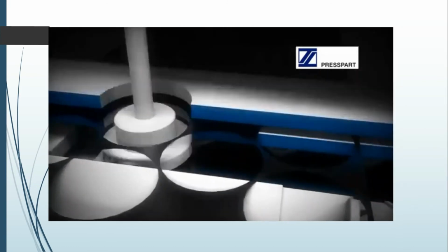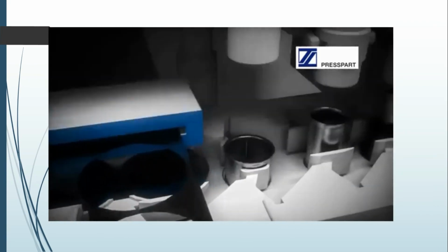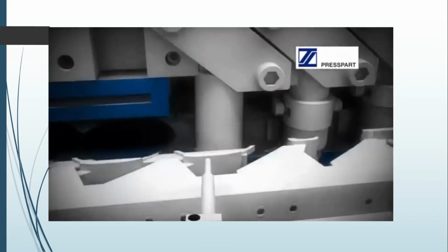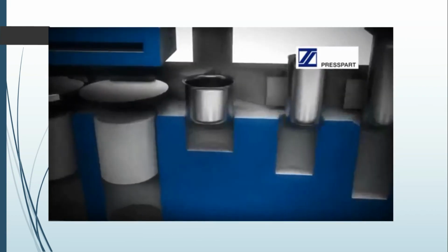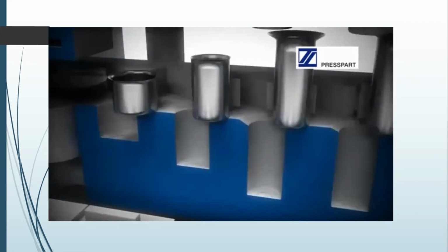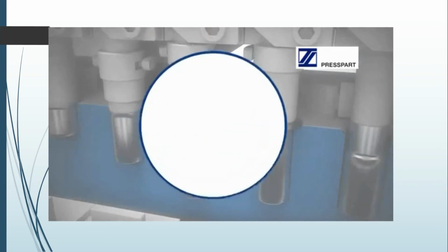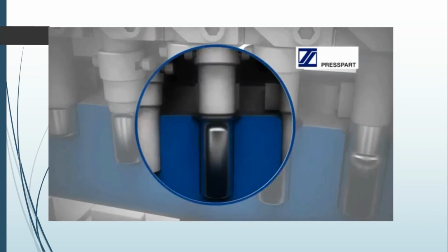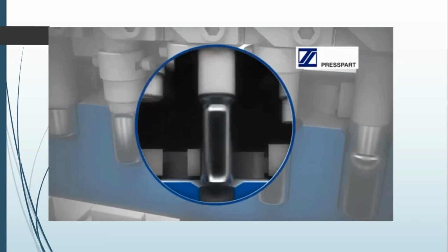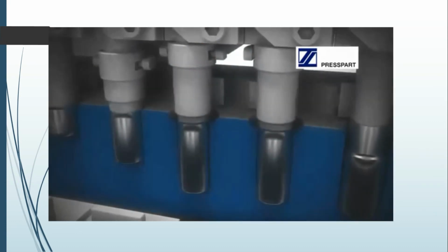Initial shearing is coming, so it makes the blank. When the blank is made, a series of drawing processes is applied, you can see one by one the reduction taking place, changing its dimension from bigger to smaller. Then it's moving to another end. The final product we will get by punching the die, how it's making, then it's taking back and slowly moving.